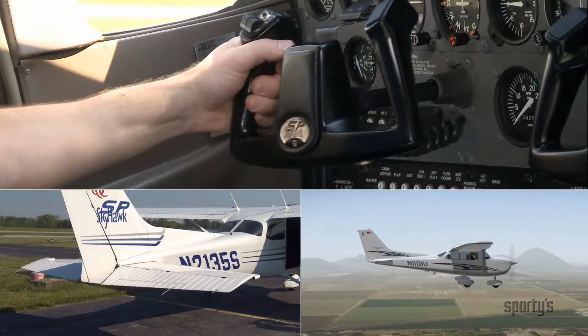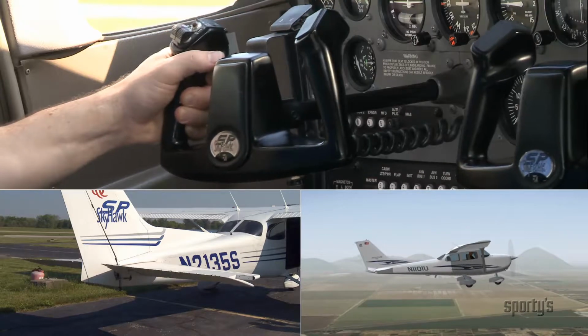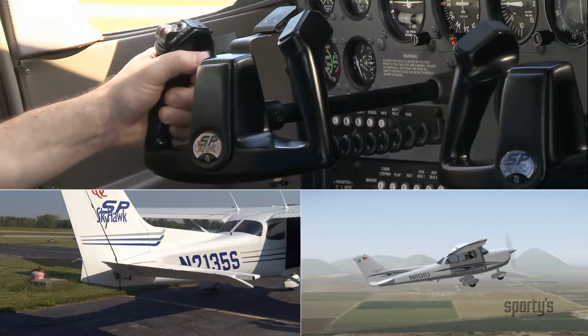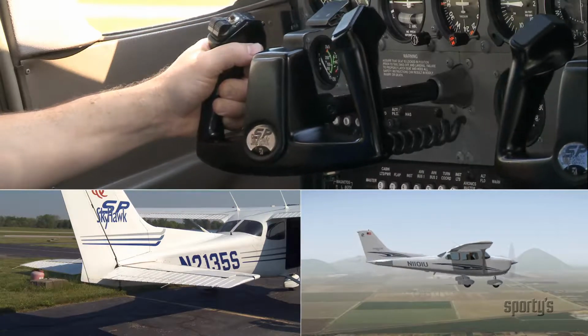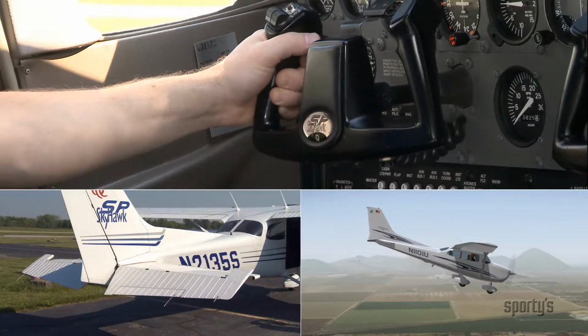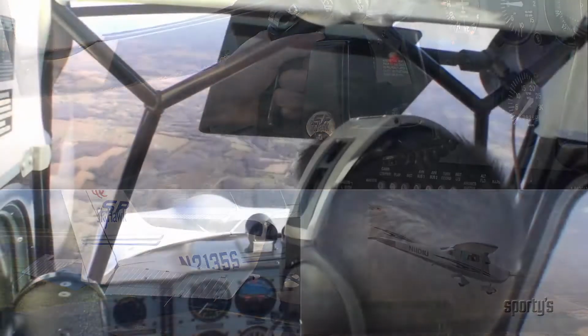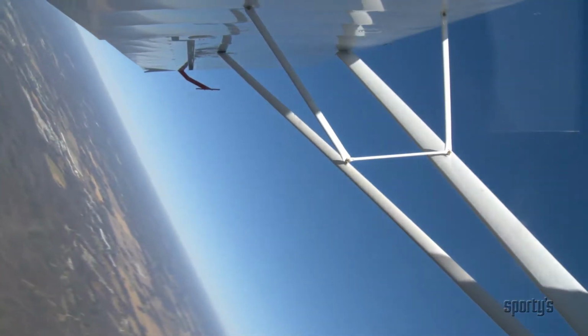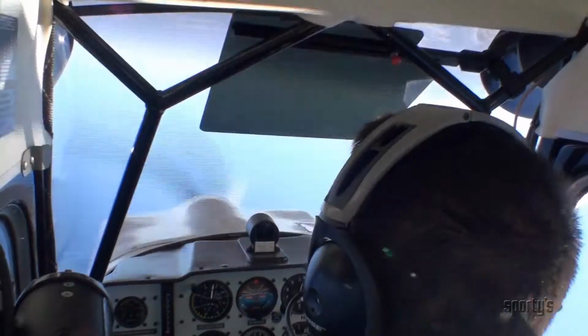Pulling the yoke back moves the elevator to rotate the airplane around the lateral axis, pitching the nose up. Conversely, pushing the yoke forward will move the elevator, pitching the nose down. But if you've seen an airplane upside down, you'll realize the pilot of the inverted airplane has to think in terms of the nose moving toward or away from him,